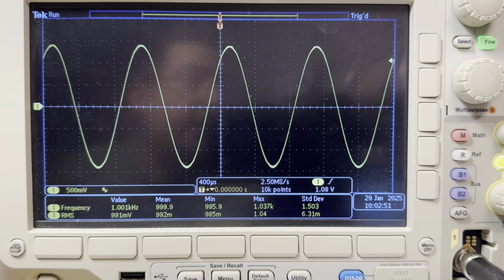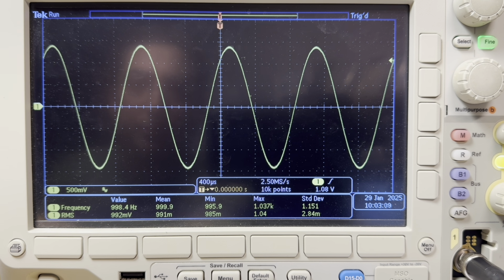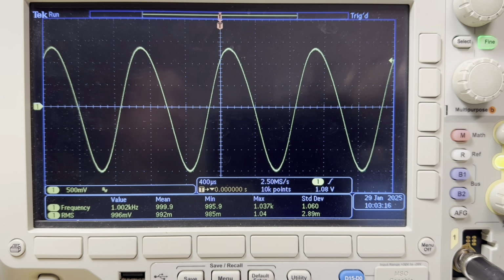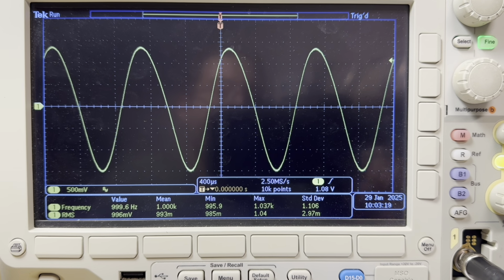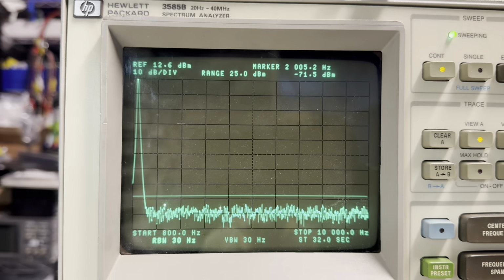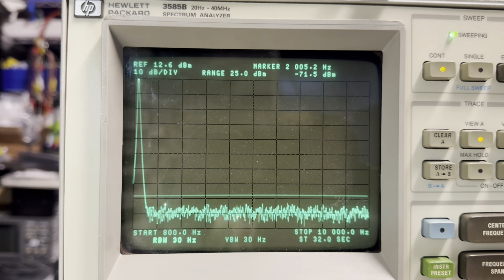Here we go at minus 50 dB. This is down to 0.3% distortion, and we see that there's really no change there from that point on, and you're not going to see anything else because the change in the sine wave is so small compared to that distortion product that we're adding in that you really can't see that much change. All right, back to our 10% sine wave.